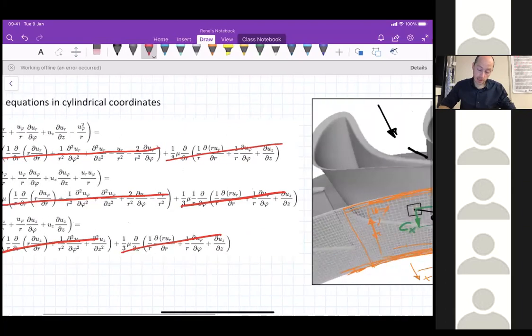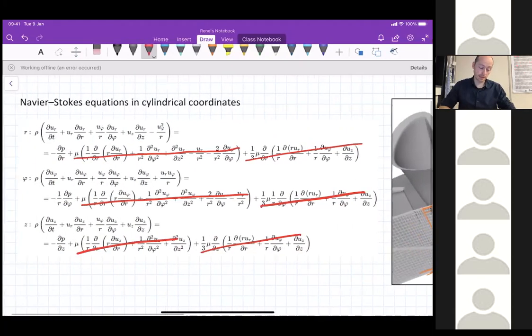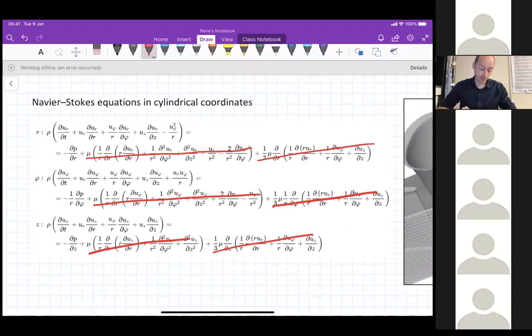So, but I would like to see if I can come up with a simple relation here that can describe maybe pressure gradients and velocities in this plane. Okay, and you already know what this will end up with, but I show you this in a very complicated way by using the Navier-Stokes equations. And then you can see that here also, if I assume that the flow is steady state, then all the temporal derivatives are equal zero. And you can see they're all partial derivatives, right? They have also partial derivatives here because all of these quantities inside the Navier-Stokes equations, of course, are function of more properties.